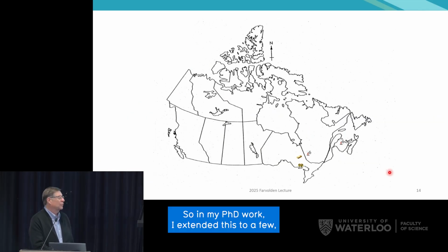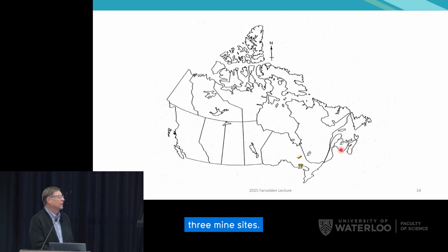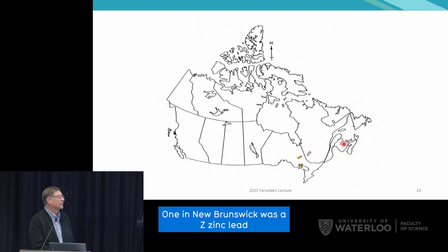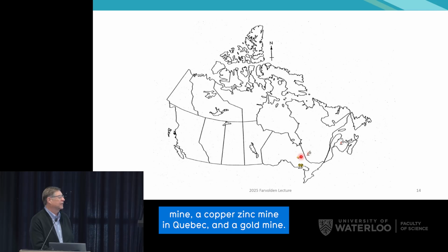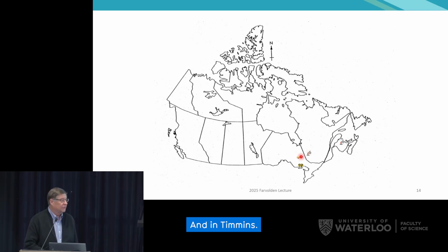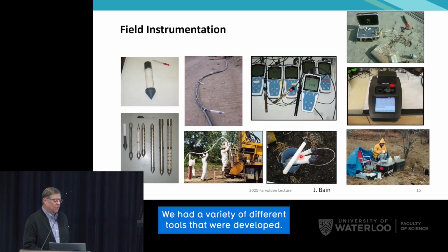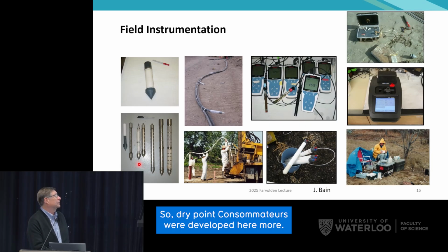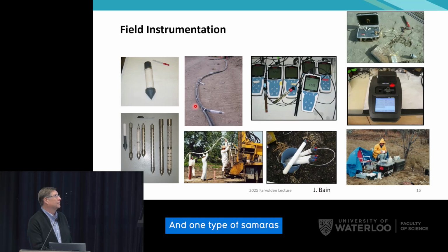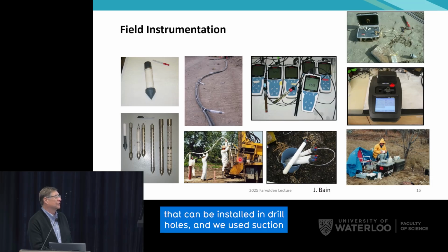So in my PhD work, I expanded this to three mine sites. One in New Brunswick was a zinc-lead mine, a copper-zinc mine in Quebec, and a gold mine in Timmins. We had a variety of different tools that were developed. So dry point piezometers were developed here at Waterloo, and bundle-type piezometers that can be installed in drill holes. And we use suction lysimeters for extracting water from the vadose zone.